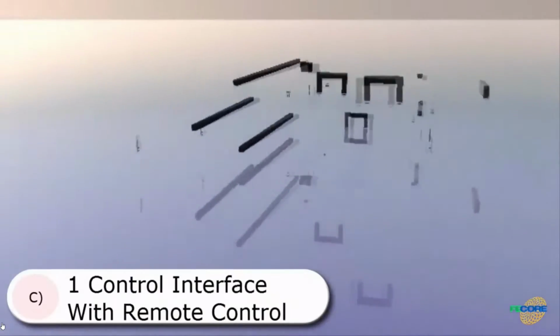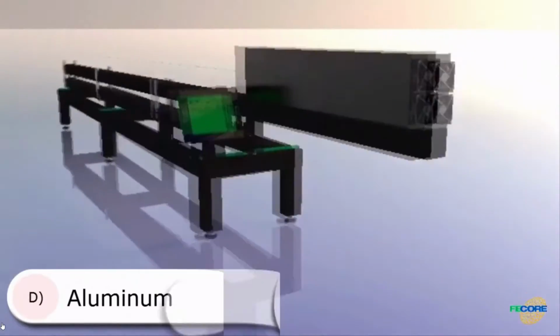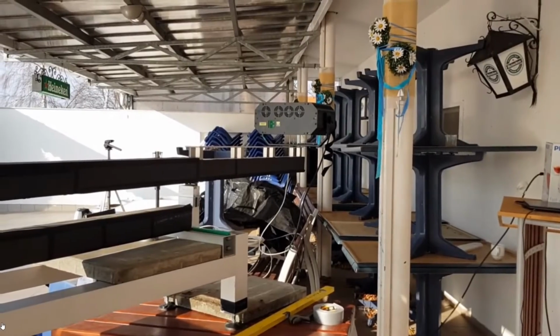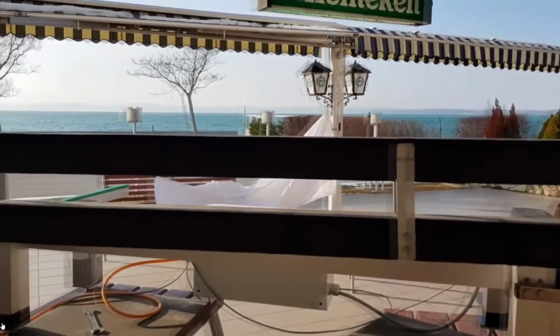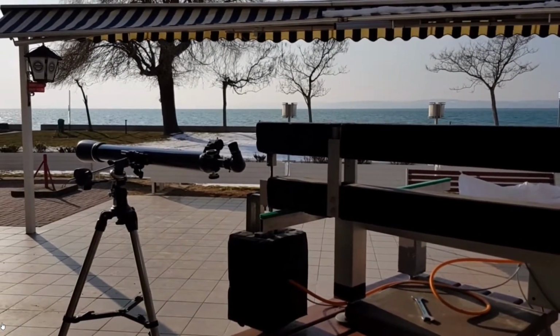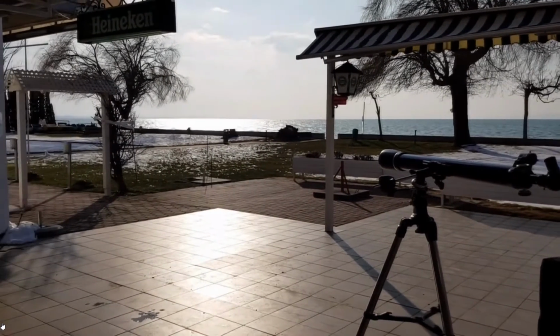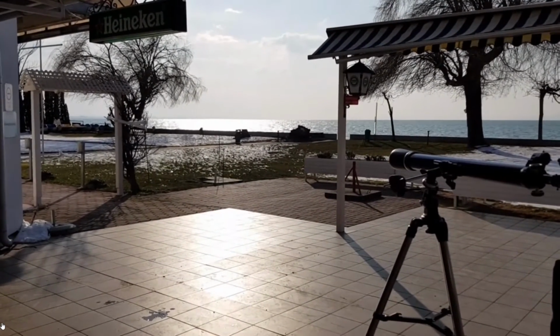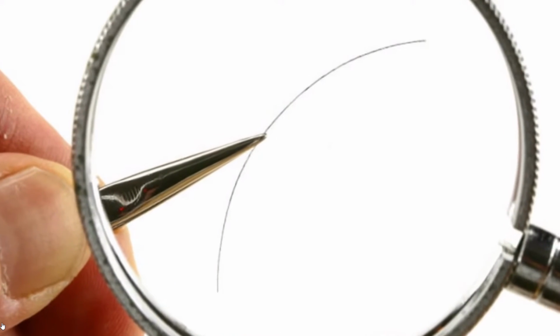This was accomplished with two high-tech stepper motors capable of making movements as small as 1/10,000th of a rotation. That is equal to 36 1,000th of a degree. This rotation movement was transferred to a bolt with fine threads 1.5 millimeters apart. That meant the rail where the laser was attached could be moved in steps of 15 100ths of a micron. That is less than 1/1000th the thickness of the thinnest human hair.